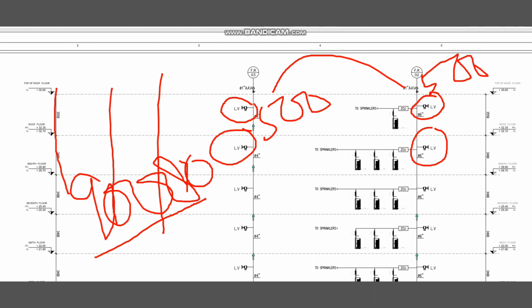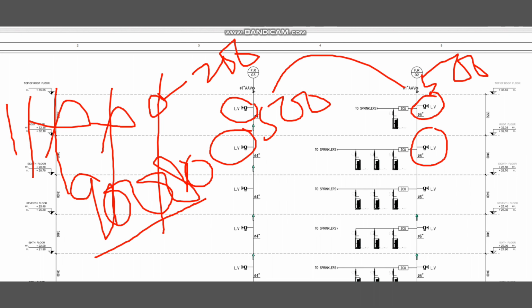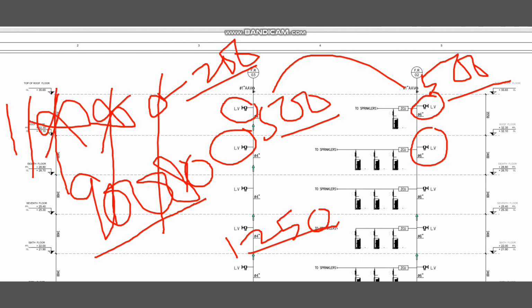Here I told you the maximum is 1250 GPM. Even though you have 10 standpipes, that is not an issue. The maximum is 1250 GPM only. So for the third standpipe you have to consider only one landing wall, so it will be 250 GPM. You don't need to consider the fourth, fifth. You don't need to consider, even though you have 100 standpipes. I'm just telling you for example. The maximum we need to consider is 1250 GPM if you have only the standpipe system. So here 500 GPM plus 500 GPM plus 250, total 1250, and we don't need to consider the additional standpipes.